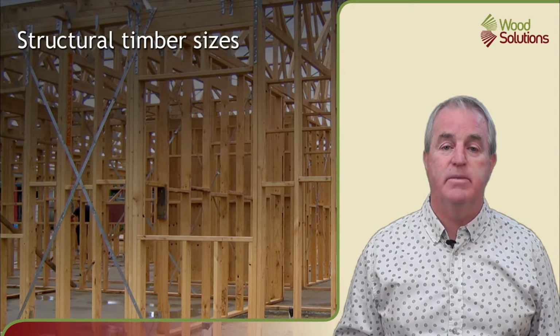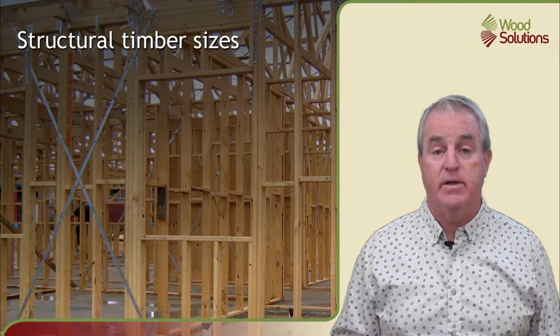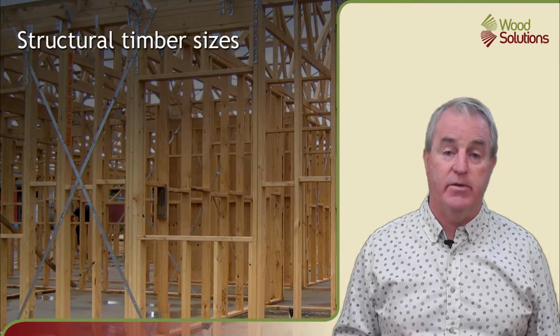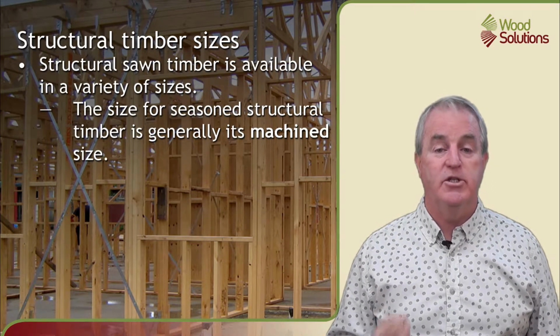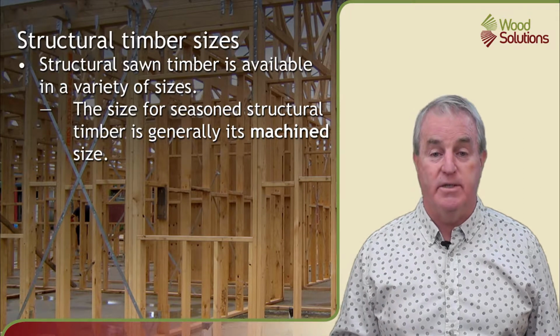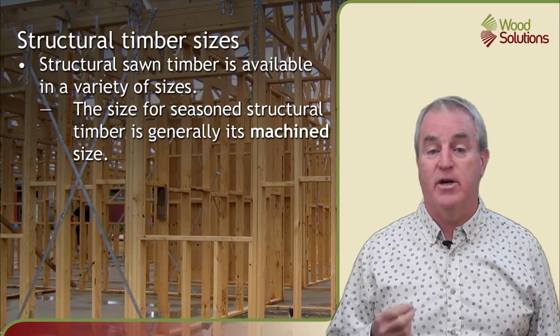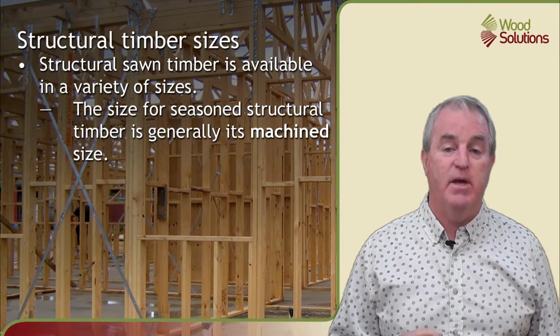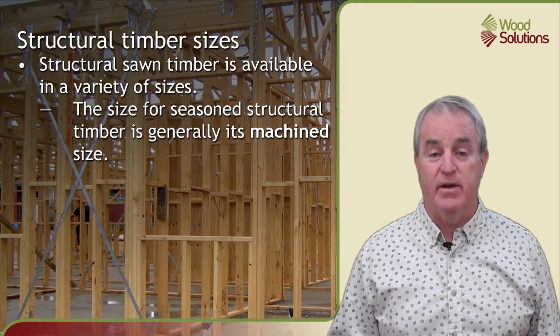As structural sawn timber is used so widely, it is available in a variety of sizes in both seasoned and unseasoned material. The size for seasoned structural timber is generally given as a machined size. The size of the timber is generally the same as the size ordered, so a 35mm thick piece ordered will be a 35mm thick piece delivered.